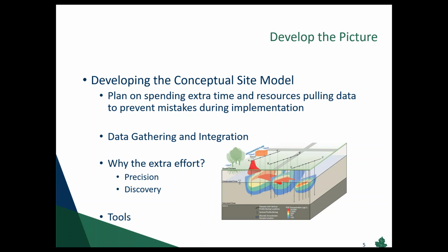So the ideal thing to do on a lot of these bigger, more complex sites is to collect a couple of soil samples co-located with your high-res site points. And so you've got some kind of point of correlation, but then use the high-res to get real-time feedback, so you're seeing what's going on a display.